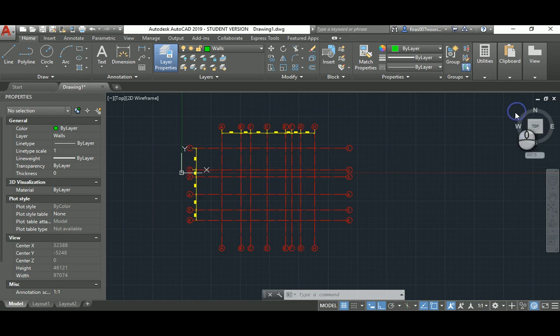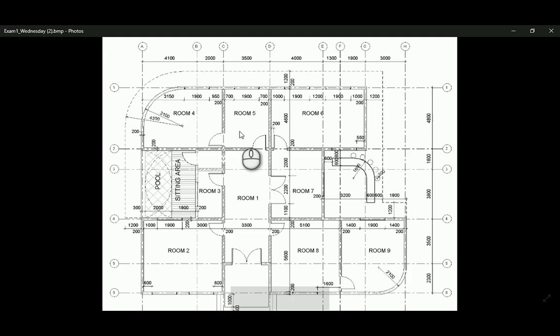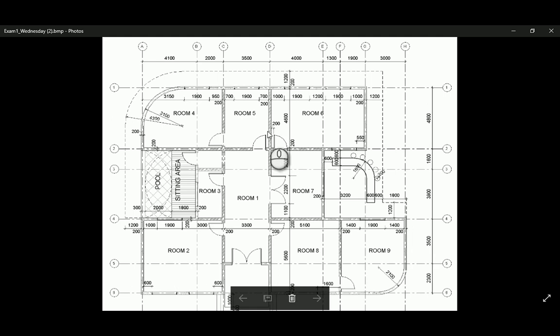Now, lots of ways to work in here. You can just offset the grid up and down based on the thickness of the wall, which is 200. And you go up 100 and then downward 100. It's gonna be a little bit long. You can draw a line and then offset the line, or you can use the polyline method. I would go and ignore, of course, all the fillets, and I will use the polyline method.